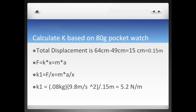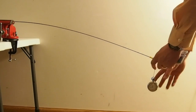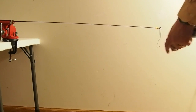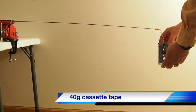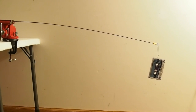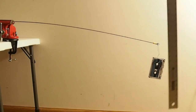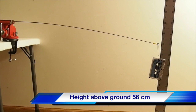So let's grab another mass. This time we'll take a cassette tape. Replace the pocket watch with this 40-gram cassette tape and measure the deflection of the rod due to the cassette tape. The number comes in at about 56 centimeters.